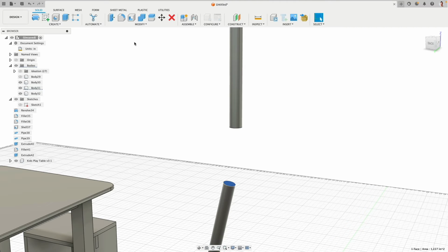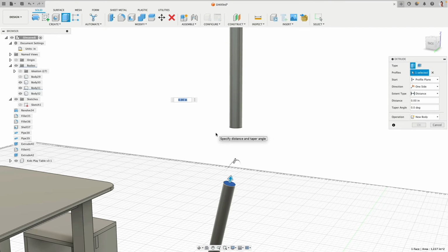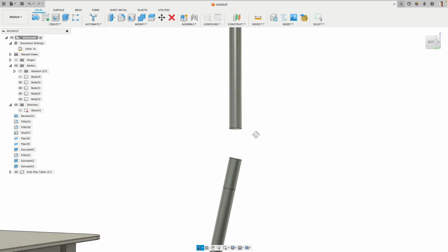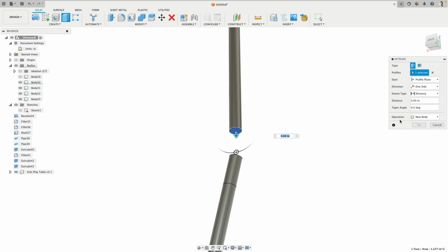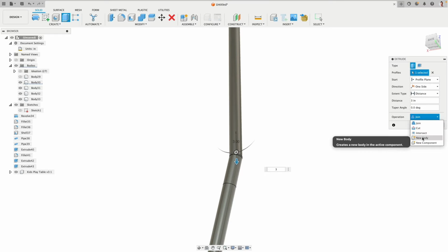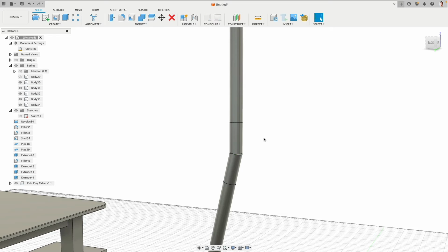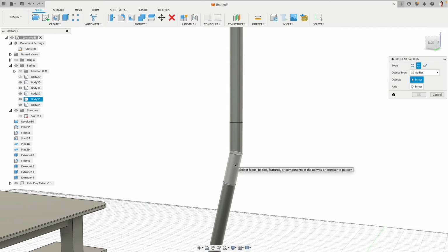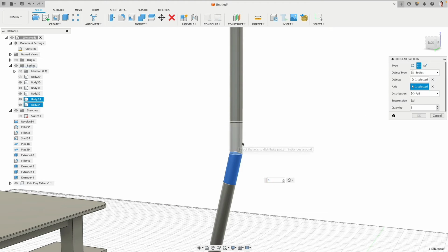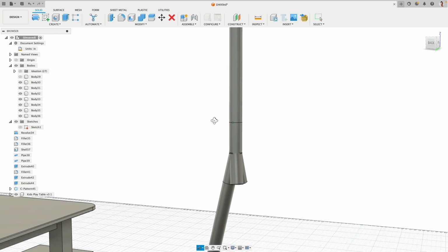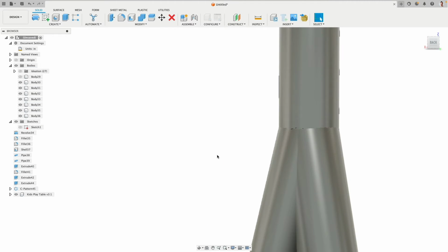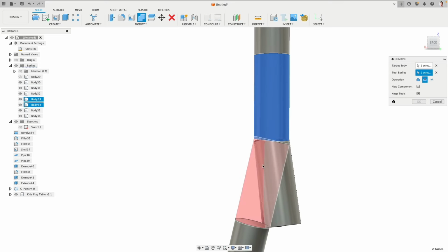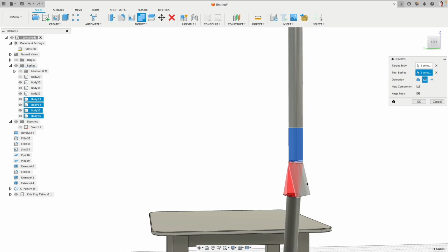Okay, then I select this one, do an extrusion, 3 inches new, right click the same here, and as a new body. Cool. This piece needs to be circular arrayed. So you around this one 3 times. Because now, if everything should work, I can actually join these 3 together.